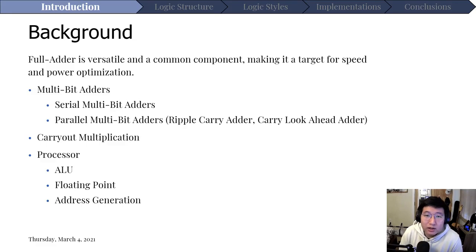So the background on why I chose to focus on full adders is when looking at generally increasing the efficiency of a system, one small piece that you can increase the efficiency of in terms of power and speed and have an overall increase is the full adder. It's a versatile and common component, and it's used in various locations. So if you want to optimize any of those, you can start with the full adder itself.